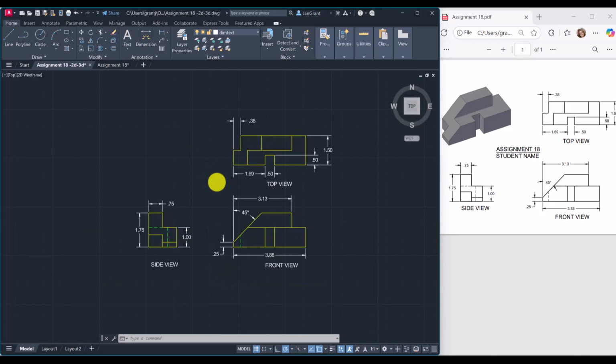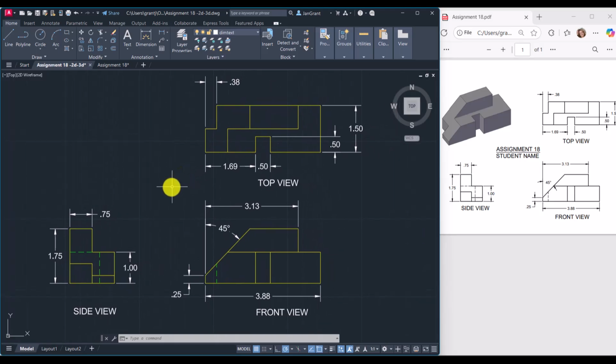All right, so while I was dimensioning, I did notice a few things. If you wanted to leave the 0.75 out over here, that's okay, or you can click on it and use grips. We already know that. The 0.25 comes over here, so you will need to click on that and then click inside. Be careful here, because you're not clicking and holding your left mouse button down, because that will move the whole thing. You're going to click inside the blue grip and then let go and then pull it to where you want it and click.